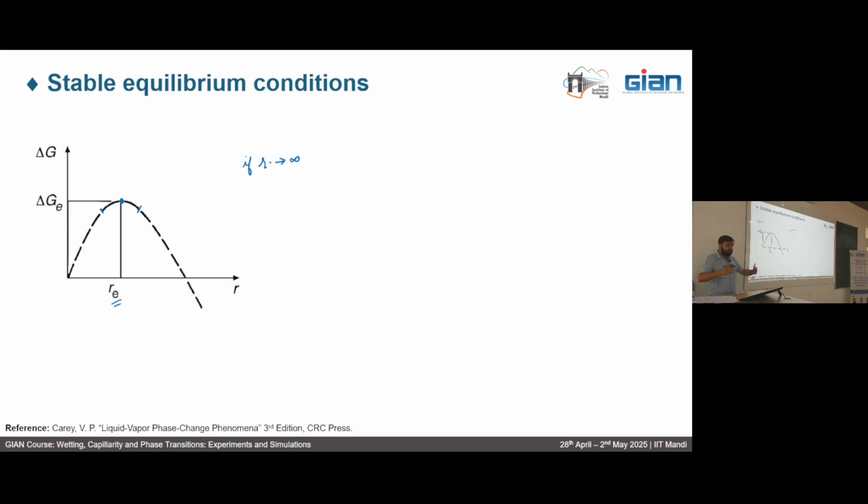The phase change could occur, the complete phase change is over, right? It means that that could be a spontaneous process. So we can demarcate by a dotted line that as R increases, your delta G reduces and it may go to a minima point. If your R approaches 0, it means that your liquid is at a metastable state. It means that no phase change has occurred, that there is no change in Gibbs free energy. It will approach 0 here. So we'll solidify this, we will just draw this line, and this is a complete curve for your delta G versus R.